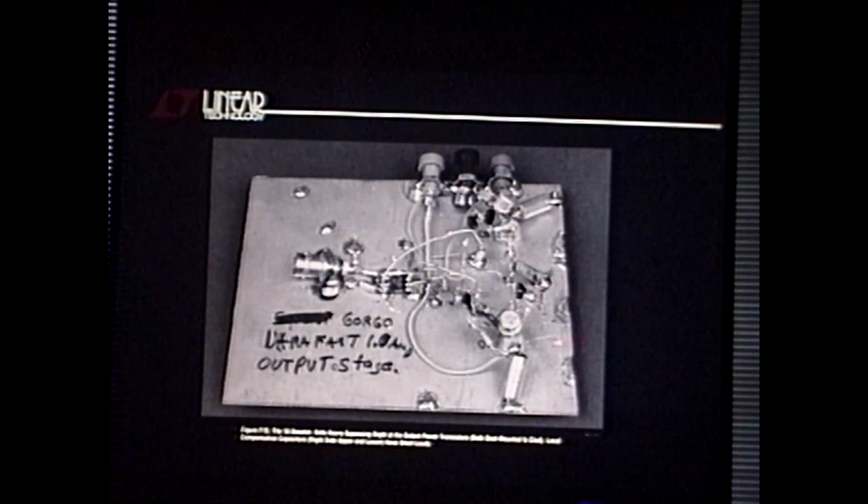Notice that bypassing the power transistors are here and here, bolted into the copper clad. You notice the bypassing? Lots of microfarads of tantalum helped by ceramic right at the point of load, the power transistors, right there.